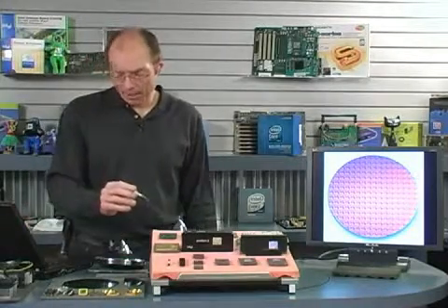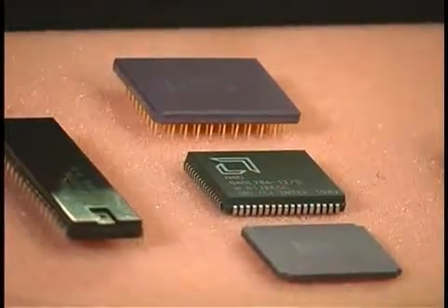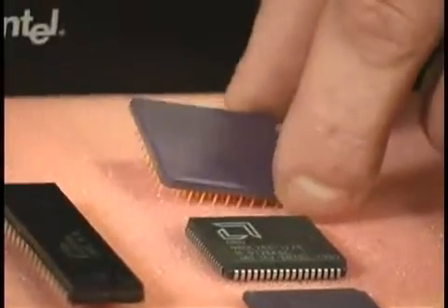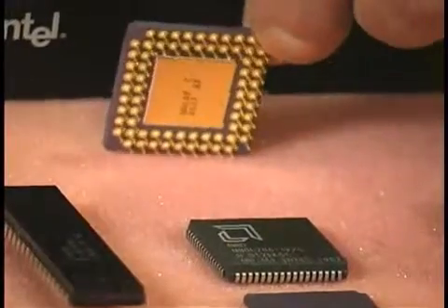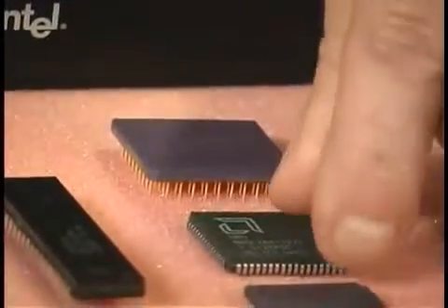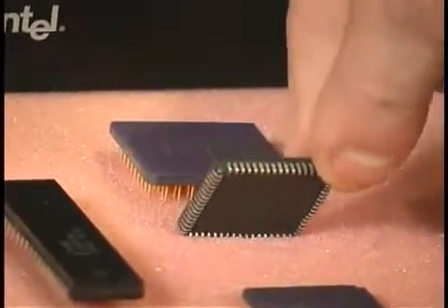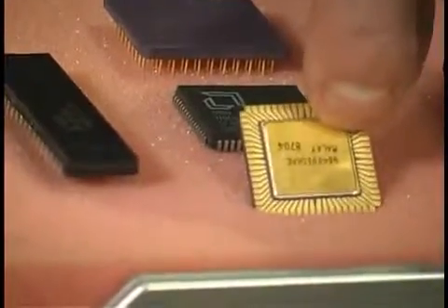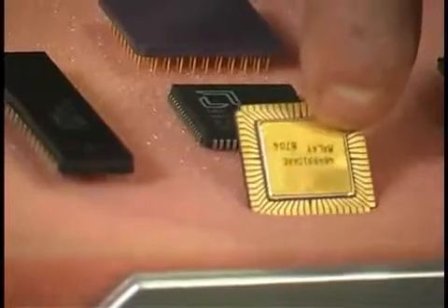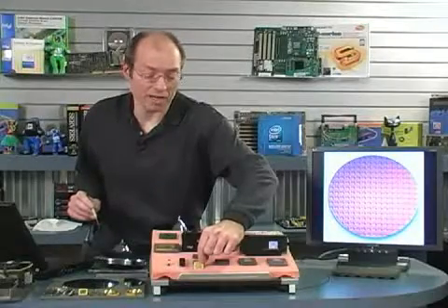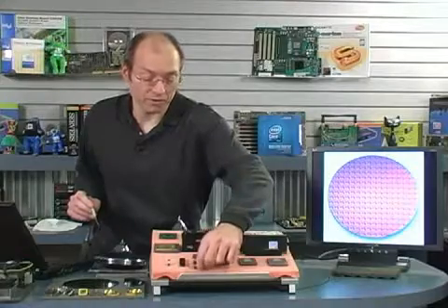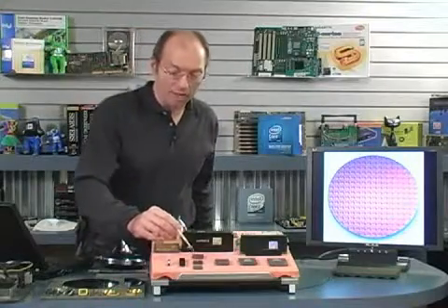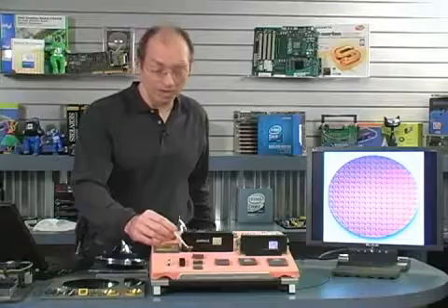Now, the 286 came out in 1982. I have 3 different examples of 286 processors here. They're just a different physical configuration. This first one uses pins that plug into a socket. This is a different design which uses pins around the edge of the chip. And then this one had no pins. The pins were actually in the socket on the motherboard, and there were just lands around the chip. Now, what's interesting is that just in the last few years, this type of packaging has returned, and most of Intel's processors now use this land grid array, they call it. So at this point, processing speeds went up to about 10 to 20 megahertz.